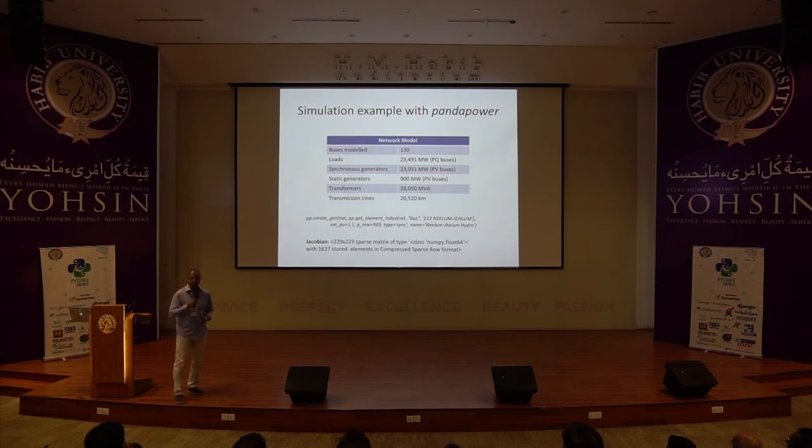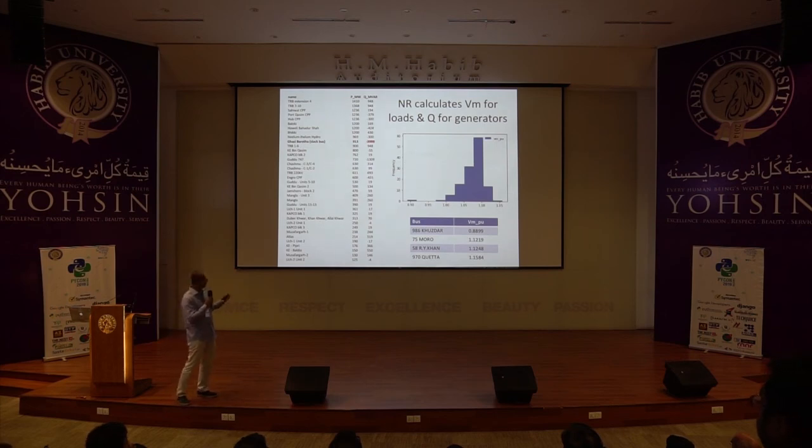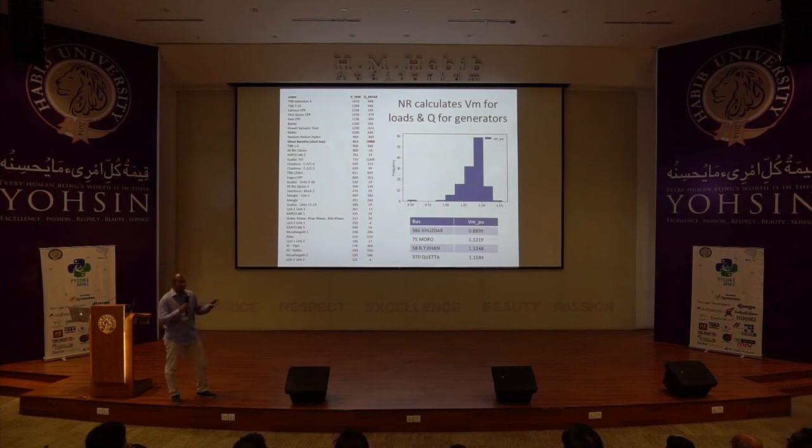Okay, so computationally, I can compute this in an IPython notebook. It's not a problem. When I actually run this computation, you'll see the chart on the right is a histogram which shows the voltage at these 130 buses for the system to remain stable. And NEPRA allows plus or minus 5% on transmission. So if 1.0 is your base, you can see most of the nodes are actually above what is allowed.